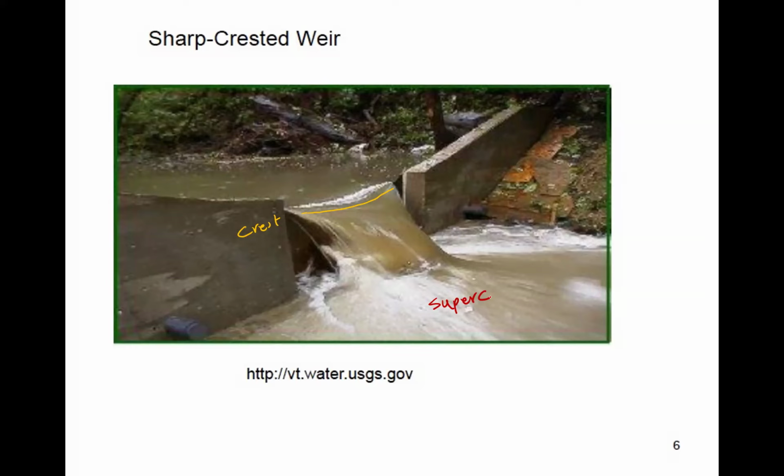Potentially, it could start depositing sediments and fill up. And over time, you might be changing the longitudinal slope of the stream. Yes, downstream, you're creating supercritical flow, but if you contain it in a relatively small space and convert it back to subcritical, you could use this to manage the stream and control erosion and so on.